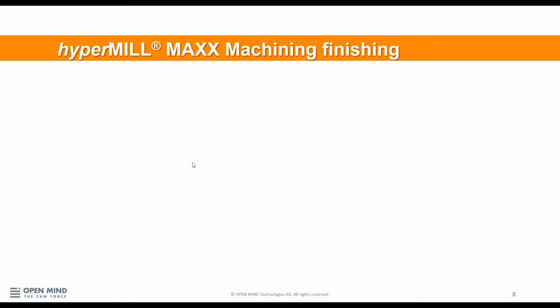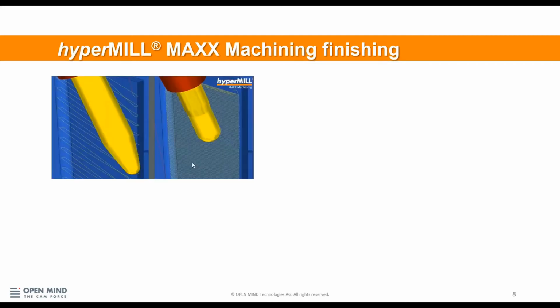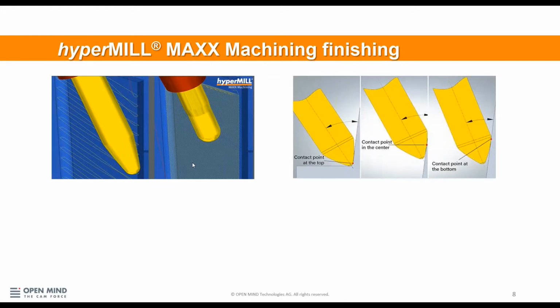Members of our innovation team observed large cycle times for finishing surfaces. Many CAM solutions have techniques to reduce roughing times. This only exacerbates the large finishing times. The idea of using a larger radius or barrel cutter came to mind. Then the conical barrel concept was applied to provide holder clearance and enable shorter cutter stick out. Then the process was enhanced with variable contact point, smooth links, indexing, and more.